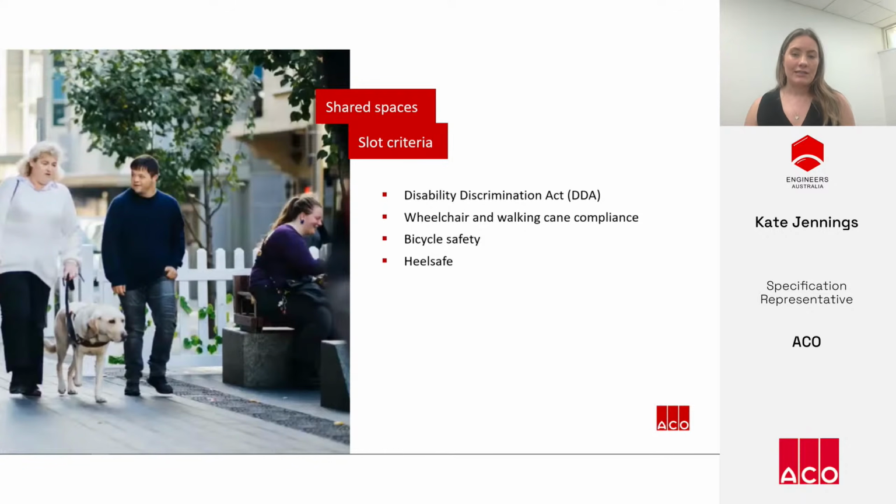The next element to consider is slot sizes, and slot sizes are critical for pedestrian safety, and we don't want to hinder accessibility for wheelchair and walking cane users. New building works must be designed to comply with the Disability Discrimination Act, which makes it against the law for public places to be inaccessible to people with a disability.